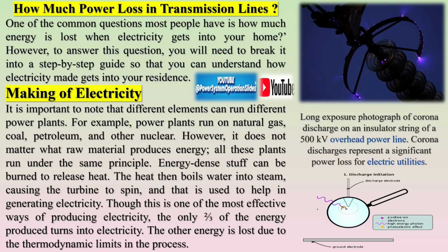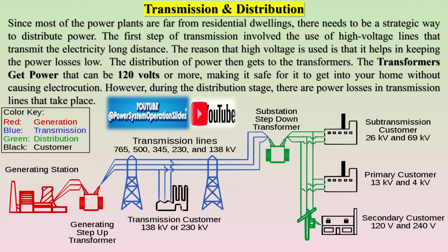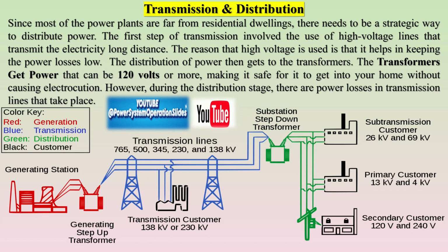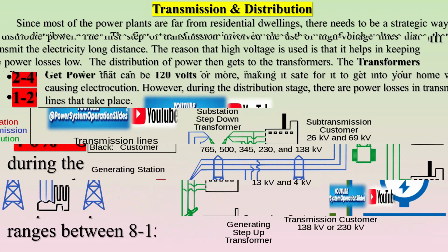These losses result from the continuous polarization and depolarization of the insulating material in response to alternating current (AC). Although minimal in most transmission lines, dielectric losses are more critical in cable systems and EHV systems that use oil or gas insulation. Another important category of losses is inductive and capacitive reactive power losses.